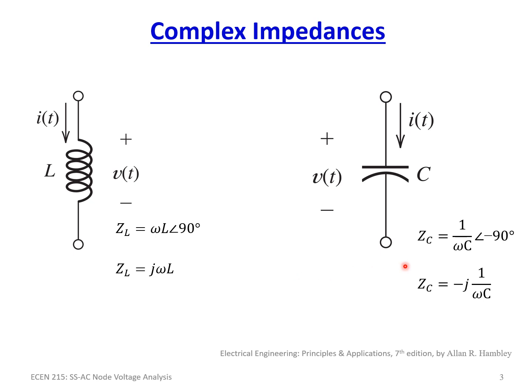A capacitor, by contrast, is similar in that it's 1 over omega C with a phase shift of minus 90 degrees. Again, omega is the frequency and C is the actual capacitance of the component, in this case say 1 microfarad. So ZC in the rectangular form is minus J times 1 over omega C. Notice this corresponds with a positive 90 degrees being a positive J in the rectangular form, whereas the minus 90 represents a minus J.